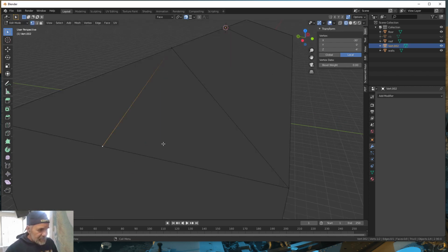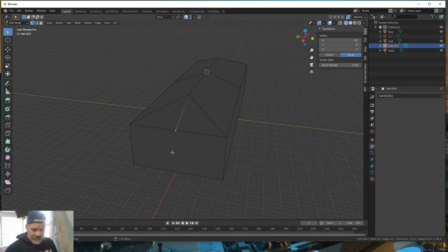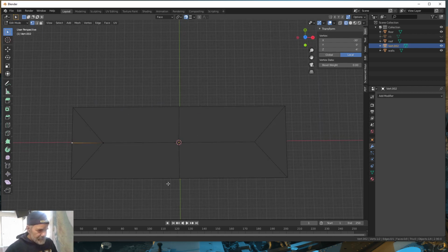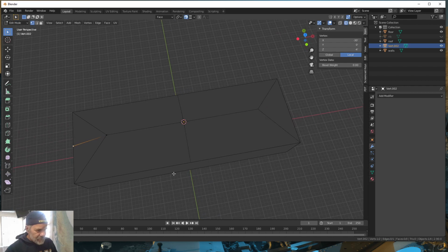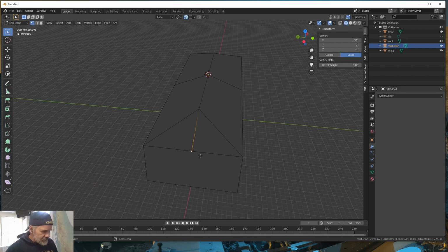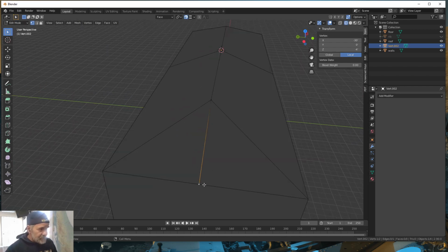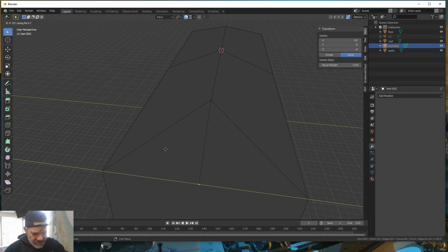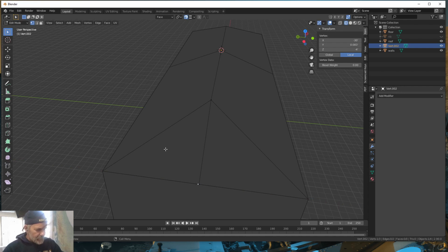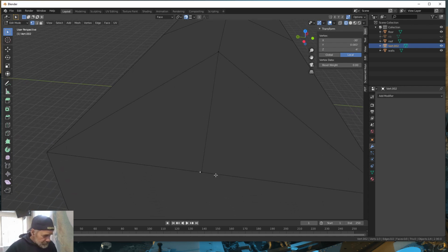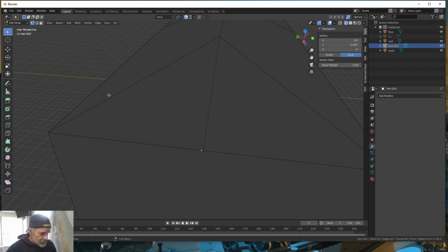All right. And then I've got to figure out which orientation I'm at here. So I'm going to tilde top. All right. That's top. So to the right is negative. All right. So I'm going to select that vertice and I'm going to extrude Y minus 0.08. No, I went the other direction. That's all right, 0.083. It doesn't matter. Just pick a direction and go for it. All right, so we went, oh yeah, positive Y. I was thinking X. All right, so we went this way 0.083 inches.